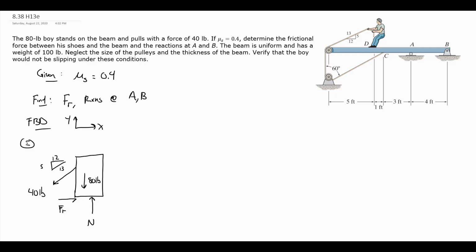So that's our complete free body diagram. Notice here for that normal force, since I don't know anything about his width, I'm not putting in that unknown distance from a pivot point. I'm unable to check for tipping. I'm only looking for him slipping in this problem.